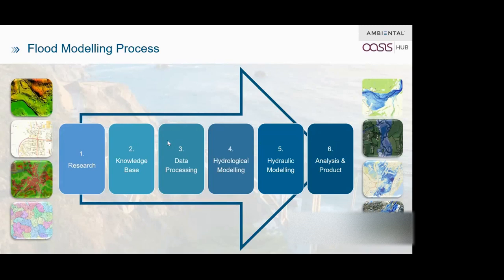So then moving on to the hydraulic modelling. Everything that has been processed and obtained up to this point is then used as inputs to the hydraulic modelling, which involves running hundreds of thousands of overlapping flood simulations, the outputs of which are combined to form our flood hazard maps. For EuroFlood, we used our own proprietary 2D flood modelling software to do this, FloodFutures.